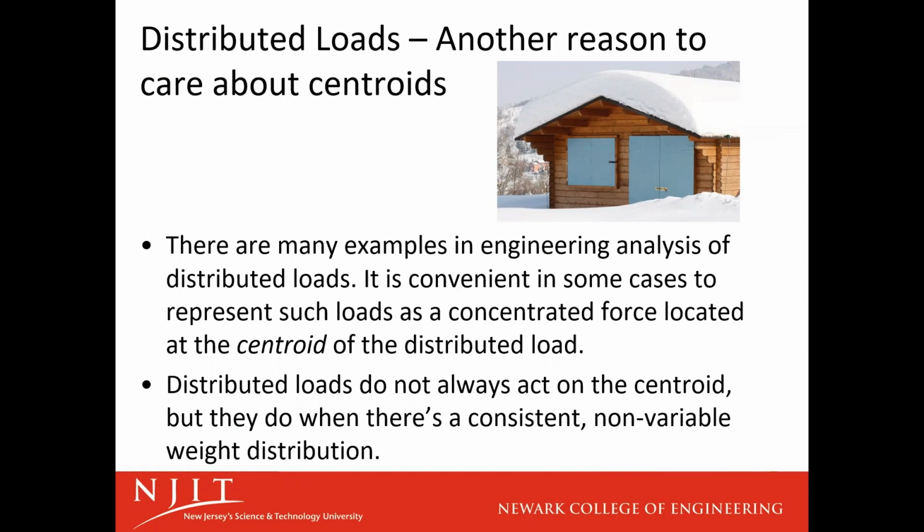So we can represent our distributed load as a concentrated point force located at the centroid of the distributed load. What that means is we're going to take the weight distribution, come up with a profile of that weight distribution, and we'll use that when we talk about area and distance. We're using them in a representative way when we look at this force profile. Distributed loads do not always act at the centroid, but they do when they're a consistent, non-variable weight distribution, which is what we're going to look at in this class.